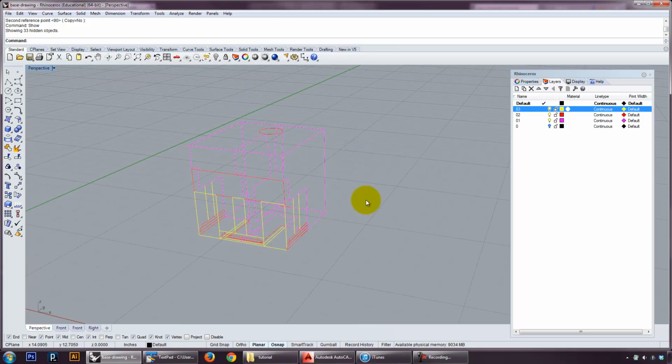And that's my scaffold. Now at this point, it'd be a very good idea to save your file, right? Because you've already gone ahead and you've created your scaffold. Make sure always to save your file frequently. Make backups of different iterations of your file so that you don't lose any work. Particularly as you model, because modeling in Rhino can be destructive. And as I've shown you, what that means is that if you're performing operations on objects, sometimes that'll actually erase the objects. And so it's hard for you to repeat that command to make another object if you've lost those pieces. So saving copies of your files can help you recover those pieces should you forget that.